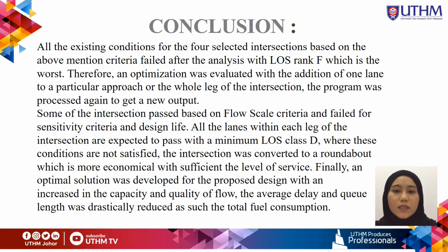Some of the intersections passed based on flow scale criteria and failed for sensitivity criteria and design life. All the lanes within each leg of the intersection are expected to pass with a minimum level of service class D. Where these conditions are not satisfied, the intersection was converted to a roundabout, which is more economical with sufficient level of service.